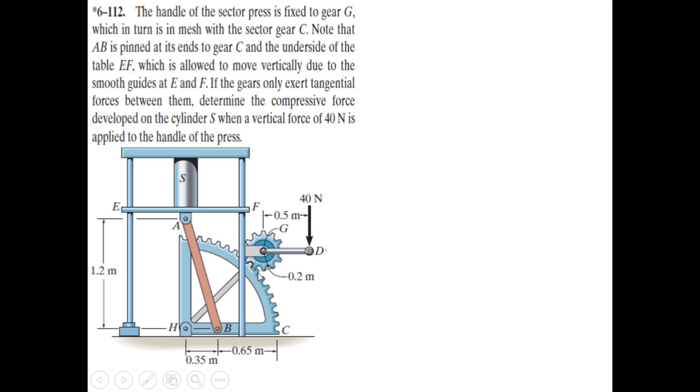So if you remember, when we were solving the problem on frame, I told you that if you are going to consider the entire free body diagram of the frame, your problem will become statically indeterminate. That is, you will have more unknowns and fewer equations of equilibrium. So that is why we have to dismantle each and every member of the frame or a machine to make them statically determinate. So the same strategy as we adopted in case of frame will be used here.